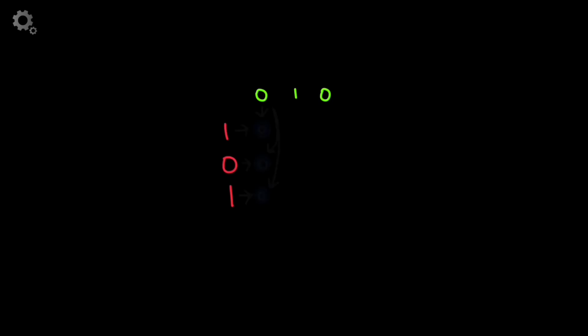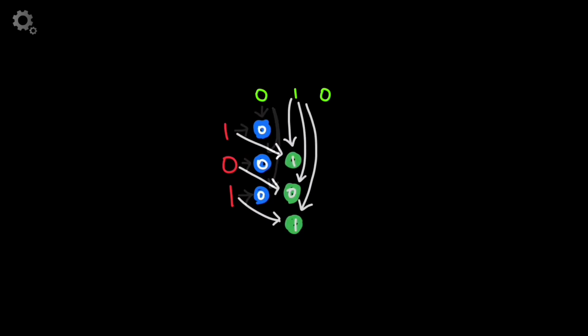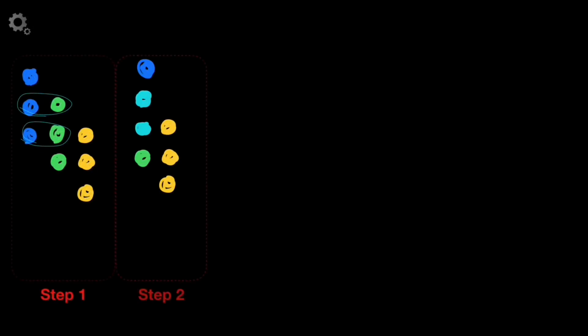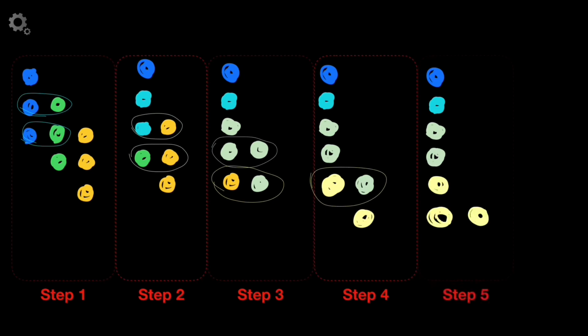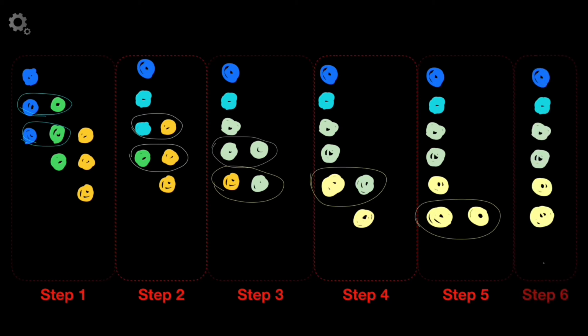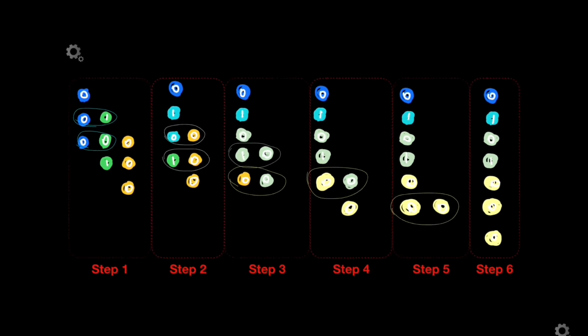Initially, two 3-bit numbers are multiplied with each other to give 3 partial products, blue, green, and orange. The 2 partially generated products from step 1 are added to give a single bit, represented as cyan in step 2. As in step 3, when a carry is generated, it is appended to the continuation bit. These additions are held until all the bits and carries have been processed. In other words, the process stops when 2 bits are left out.